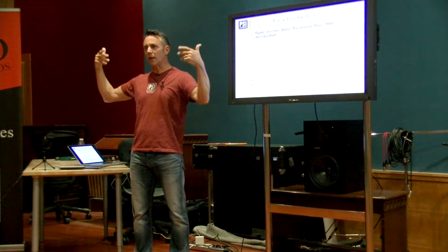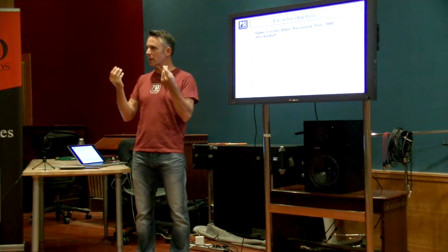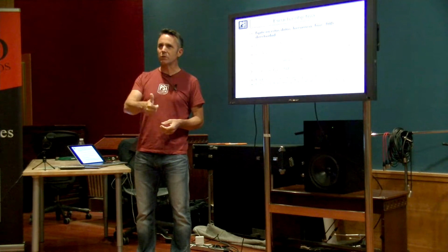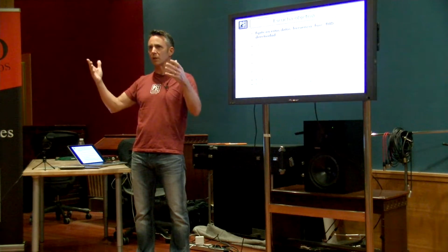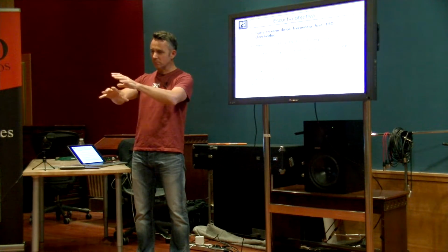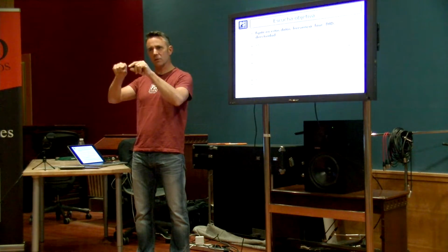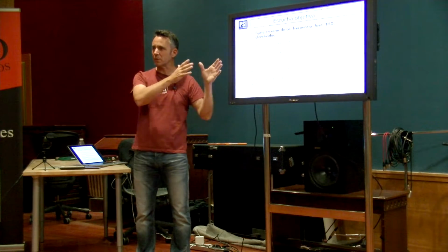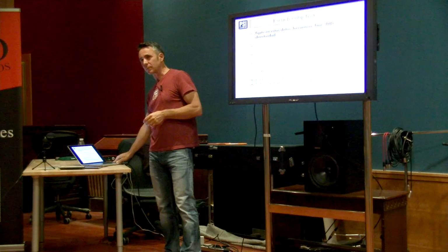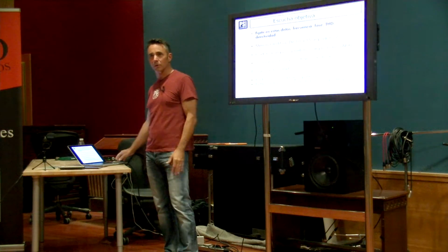Then there's all the things that you can hear that you can't measure. These little bumps in the frequency response give a little character to the speaker. So then you have to go through a lot of listening sessions with different people, different rooms, different types of music, different positions in the room to get it right. Then you say, this is the best I can do with this speaker, we're all very happy with it, boom. Now that's your reference, and then you have to copy this reference in production and do exactly the same one. And there you have to measure, I'm sorry. And you have to measure in an anechoic room, because otherwise you're measuring the room and not the speaker.